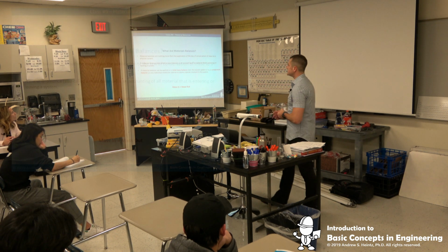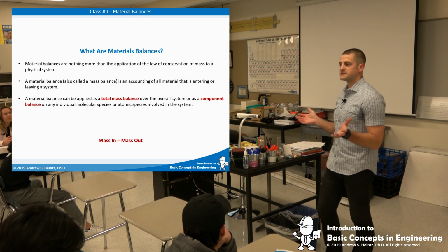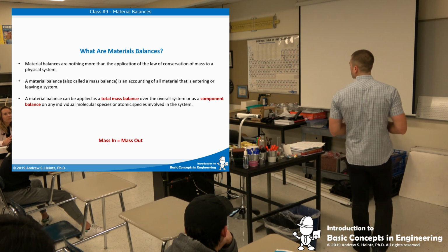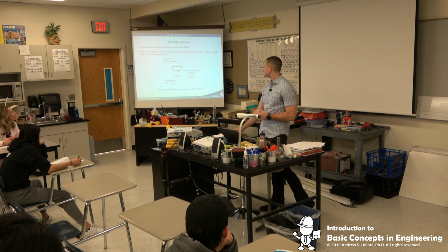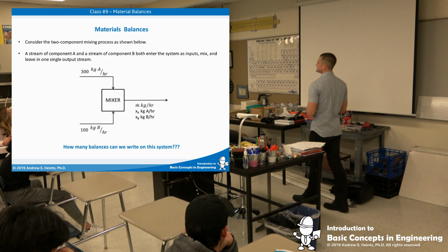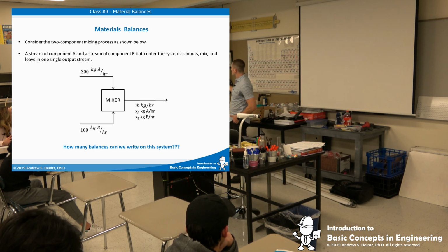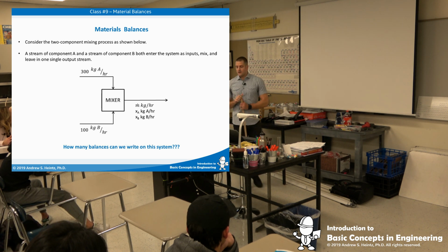So what are materials balances? Simply just the application of the law of mass balances to all of our processes. Okay? And again, we get back to mass in equals mass out. So what you're going to see is something similar to what we're looking at here, right? If we consider this two-component mixing process, we have a stream of A and a stream of B, both entering our mixer, just like we had in our block flow example. They're going to mix, and they're going to leave in one outlet stream. So this is just a mixer.